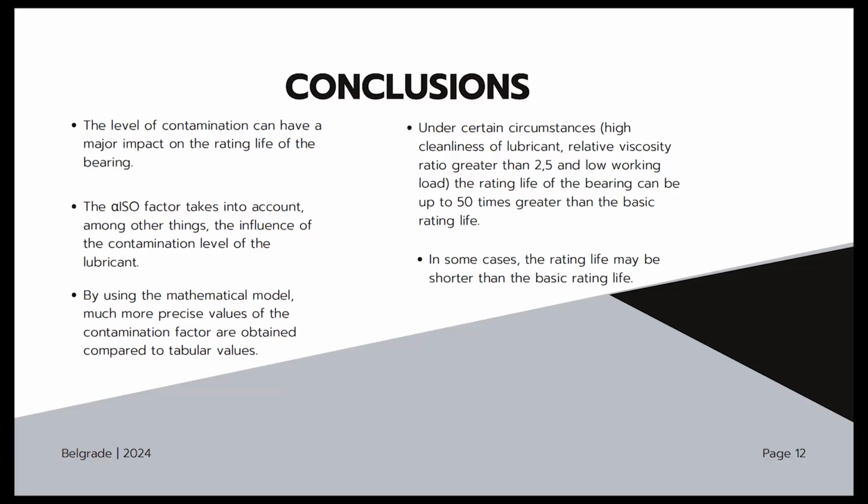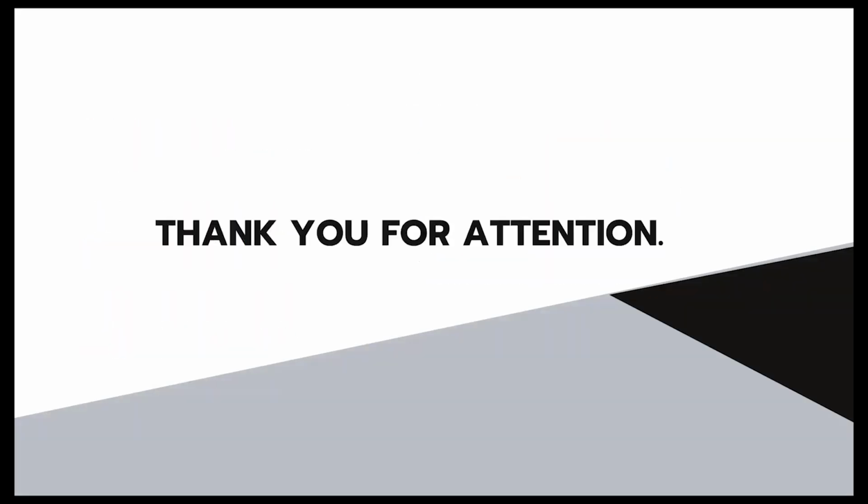And under certain circumstances, high cleanliness, relative viscosity greater than 2.5, or light working load, the rating life of the bearing can be up to 50 times greater than the basic rating life. In some cases, rating life can be shorter than the basic rating life, which is also very useful information for us as constructors. That's all. Thank you for your attention.